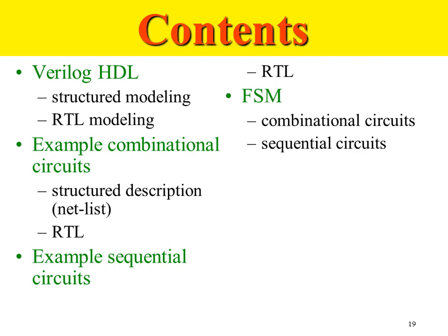Using Verilog, there could be mainly two modeling techniques or design techniques. One is structural modeling, the second is RTL modeling. RTL modeling, earlier it was called RTL modeling, nowadays it's called HDL modeling or behavioral modeling. Mostly the term that is used nowadays is behavioral modeling. It's the same thing. We'll see what that means in the upcoming slides.